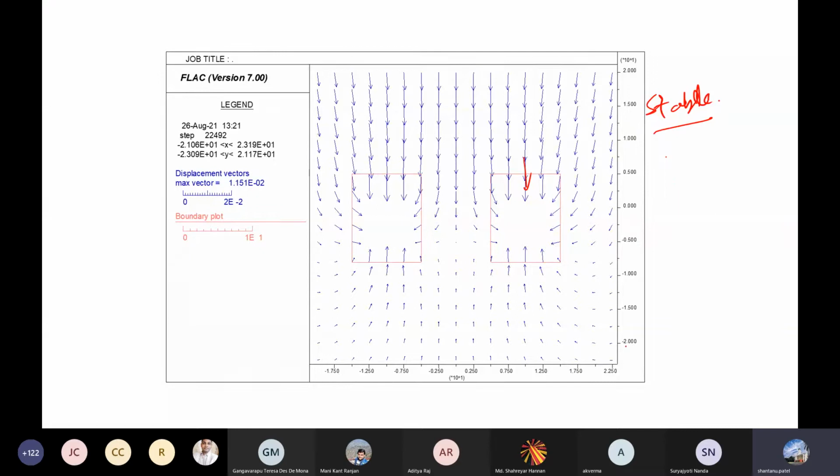For this, we need to know the strength of this material. One is the strength, in terms of UCS, which we are trying to find out. We also have different kinds of tests, and we will be discussing that in our next labs. Another thing is the displacement. For the displacement, we need our elastic constants, E and nu. So we need to know these three things: the strength, the Young's modulus and Poisson's ratio. We need to do these kinds of tests, like this UCS test.